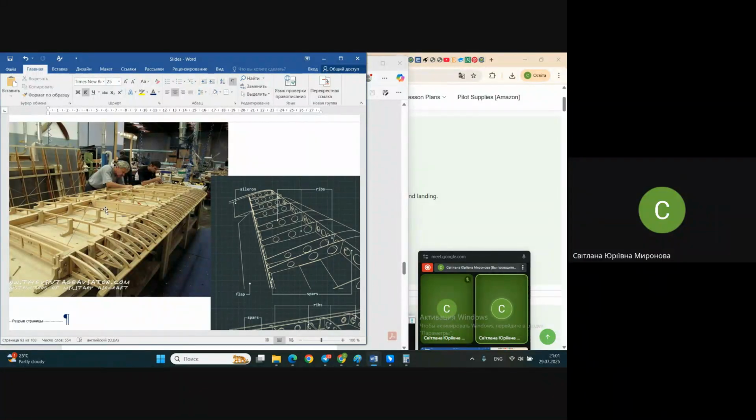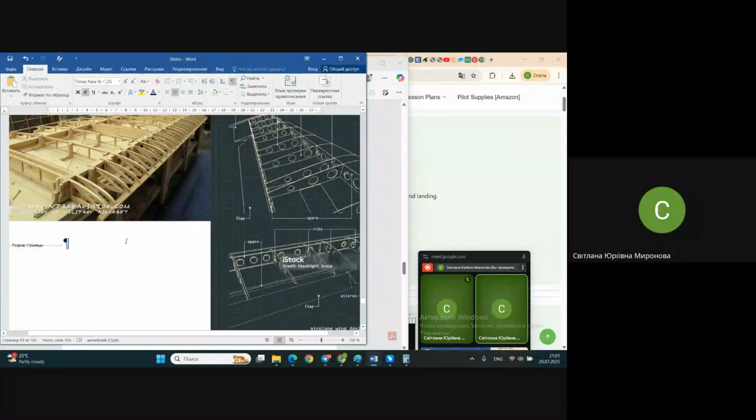All this box-like structure is able to resist torsion. When it comes to shear, it is usually received by thin elements, which are represented by ribs and by the spar.